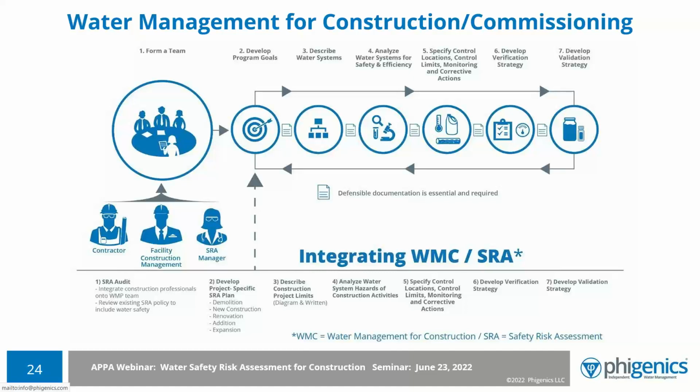And so it's things like this where you need to get familiar first. So if at all possible, go on the CDC's website and take the free online Legionella water management program training, and just take it a module at a time and start to understand these terms. Applying it then to construction is not that much more difficult.